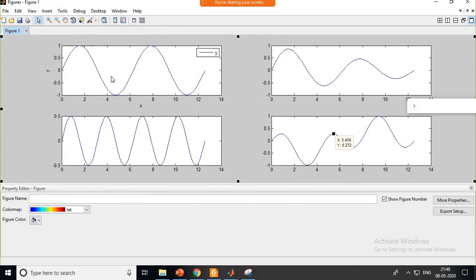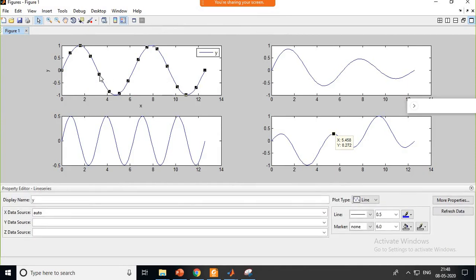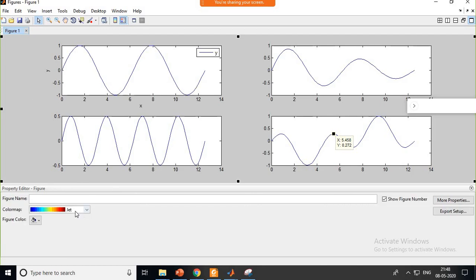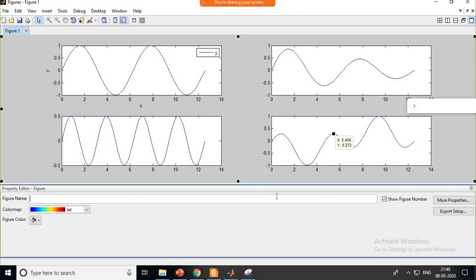In this editor plot you can now select whichever line you wanted. This is the line. Obviously in the downward place you can observe it. It is going to change dynamically the things. So here you can give the figure name. This is my figure 1. Okay. So it will display here figure 1 as this. Previously only figure 1 it was showing. Along with this I can now, this is my first subplot, I can write it. So it will display the first subplot here.